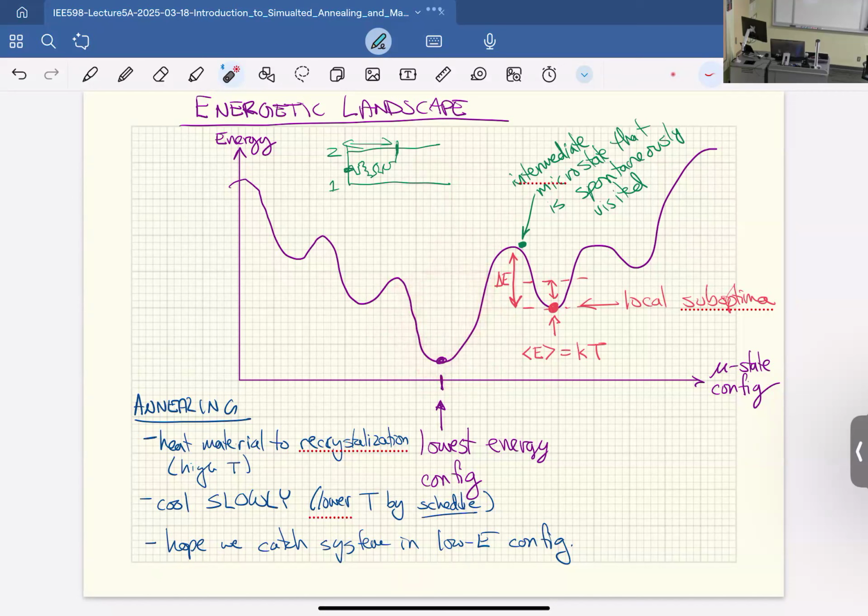And again, that's exactly what happens if you've got a bunch of, I don't know, pebbles or something like that in there, and you jiggle them fast, but slow down the way, and eventually you level out at that low energy configuration. So all the little faux mountains go away because those were higher energy configurations. That's what you're effectively doing, but you can do it for any material to settle their microstates down. That's annealing.